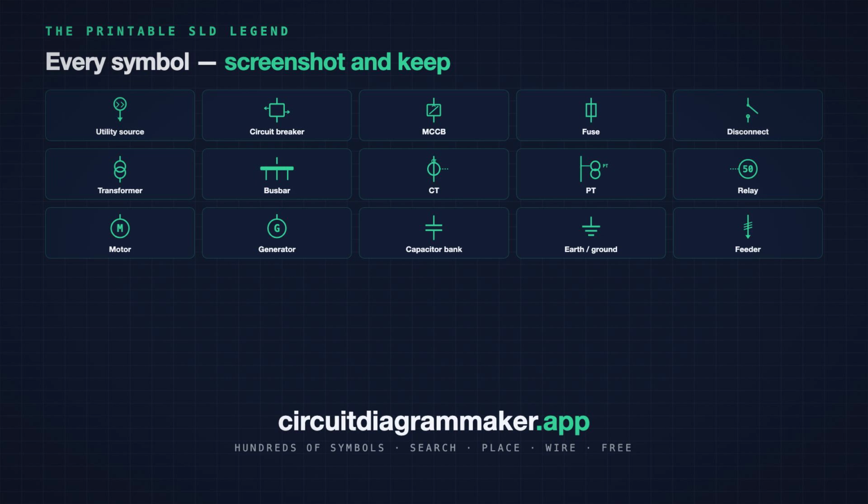Read it top to bottom. Utility, breaker, transformer, bus, feeders, and a single line diagram is no longer a wall of shapes. It is a map of the power. Keep the chart open the first few times. After a week of reading real drawings, you'll not need it.